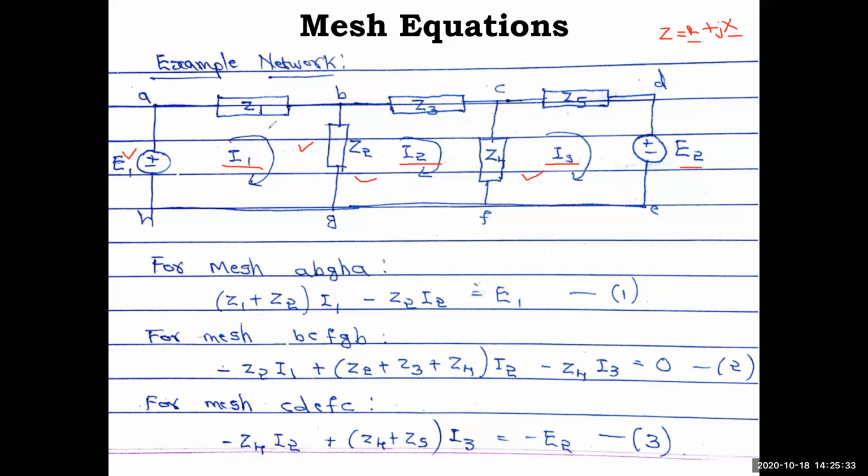One way is to write using normal KVL, Kirchhoff's voltage law around the loop. Another way is a general equation we can write, which I have written here and will show you in the second part. But first we'll try to understand by applying Kirchhoff's voltage law itself. Very simple. Now you have minus plus here, and a normal element will have a voltage drop, plus minus.